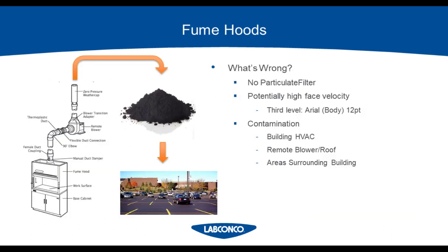So at this point, a lot of people typically ask me, why not use a fume hood? Well, think for a second about what happens when you turn on a fume hood. A fume hood is controlled by a blower on the rooftop somewhere in your building, and anything that goes through the hood is going to be run through that entire length of ductwork and then pulled into the motor blower and then exhausted through the outside into the air column above the building.